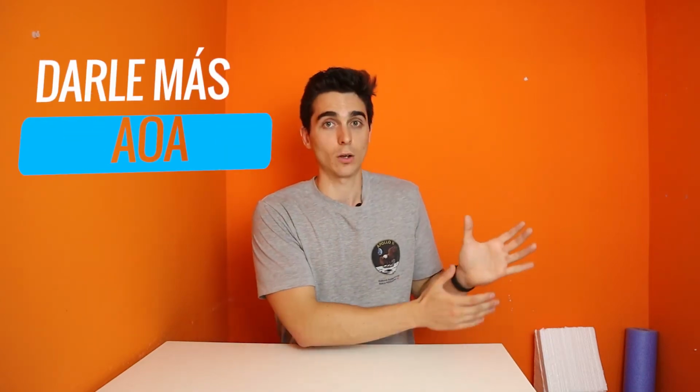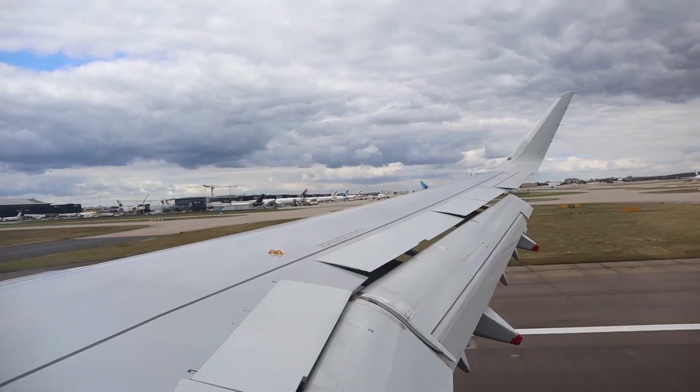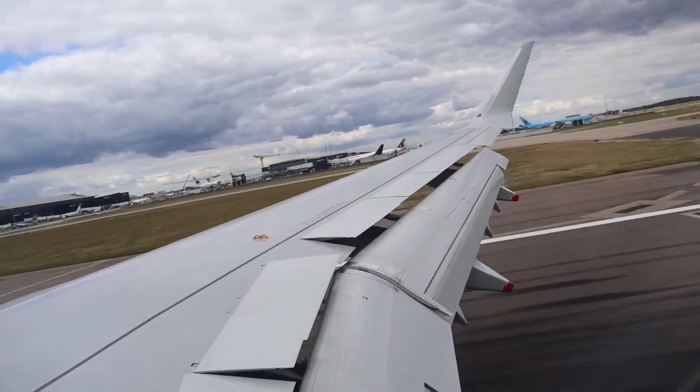So when a plane wants to take off at 300 kilometers per hour, the wing is actually seeing that the air is passing over it more slowly. Therefore, when you sweep the wing, the plane will either have to give it more angle of attack to get the same lift or go faster to get the same lift. In modern aircraft, this is addressed by incorporating flaps and slats. It has several drawbacks, but this is definitely the worst. We'll discuss the others in a future video.